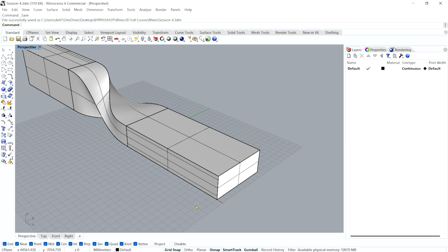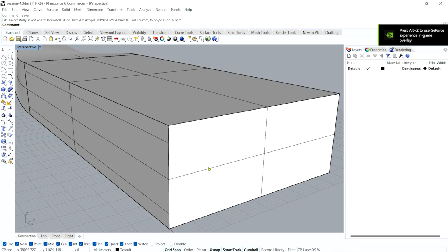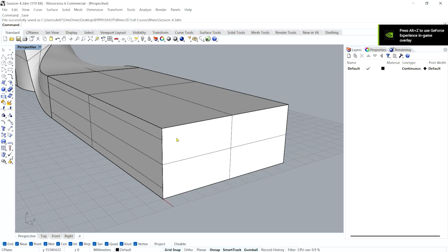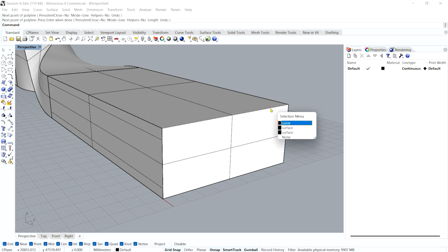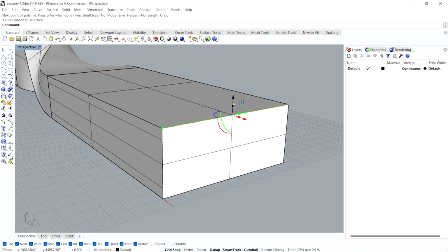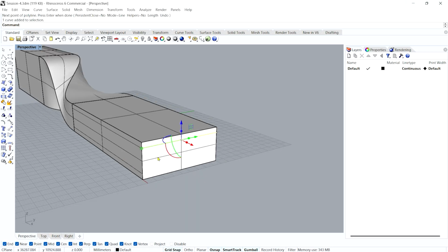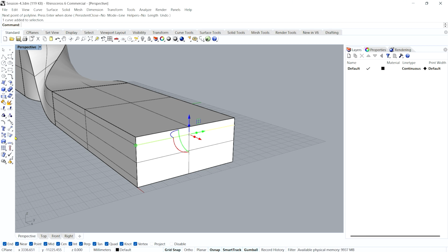two lines are done. Next, what we will do is I will continue this offset to this side also, following the same thing, using the polyline, making the curve at the top, and then selecting it, right, using the gumball, select it, minus 1500, press spacebar, and then I can use mirror command to mirror this line.